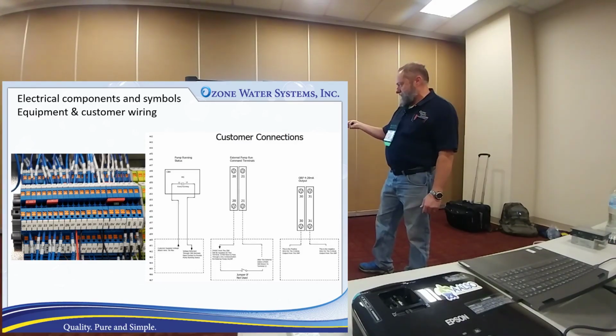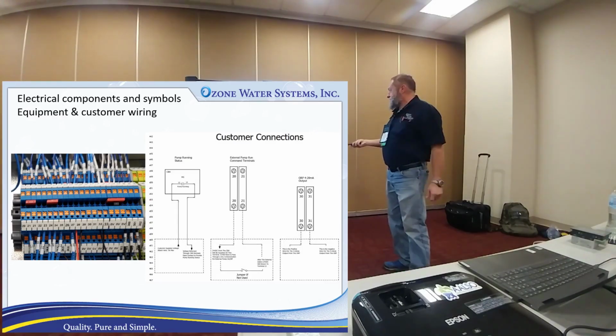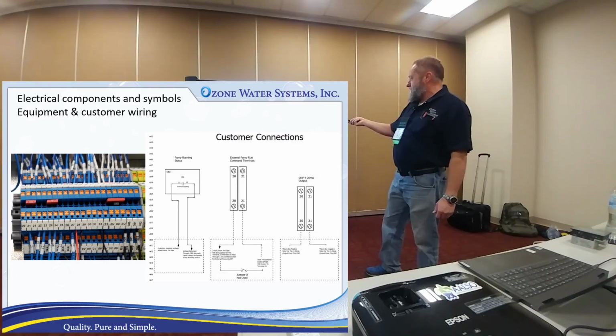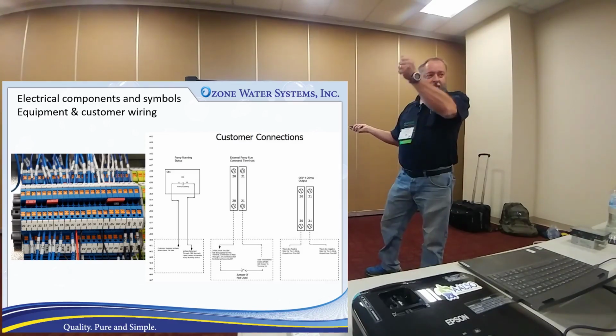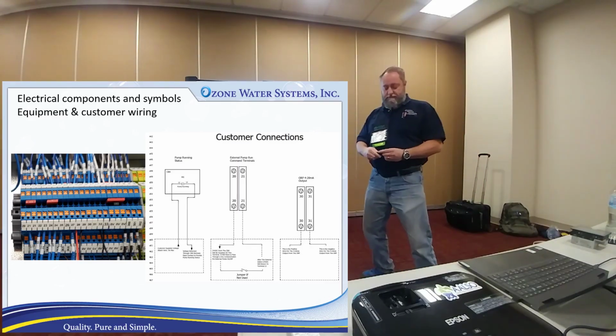Now that one looks like it's just going right to the actual M1 contactor, but sometimes we'll try to draw in actual terminals so you know what you're looking for. These could be inputs or outputs. That happens to be an input. So if you have the pump in auto, it won't start unless you give it an outside run signal.